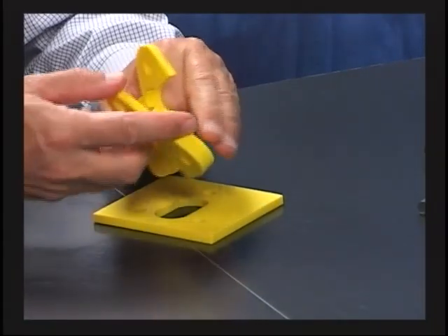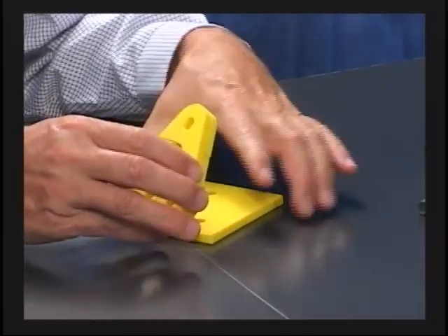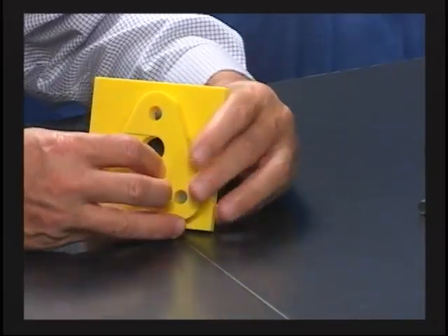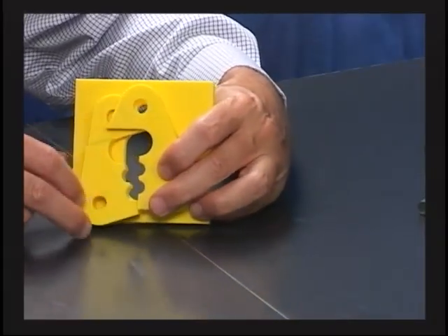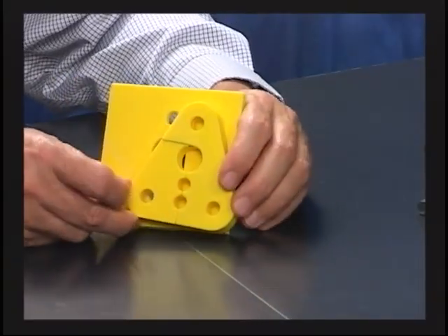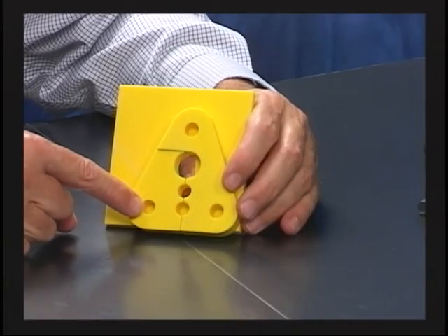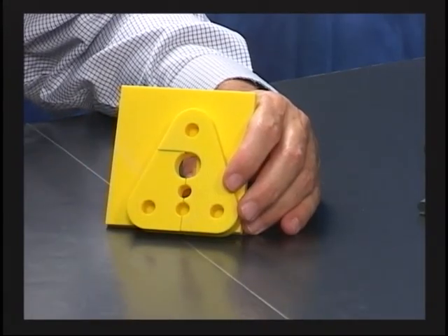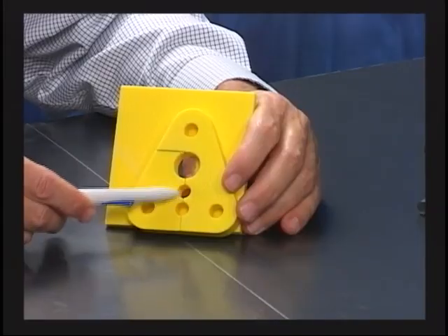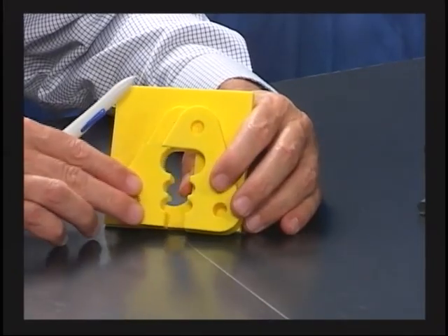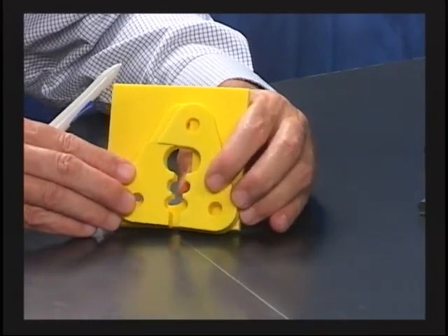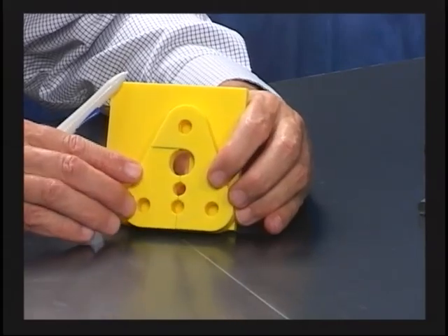Now, I see sometimes people say, well, why not just pick the holes as your datums? And I suppose you could. You could pick the holes as datums and then locate the surfaces. But the problem I thought is, if I pick the holes as datum and call those holes 0, then I'm going to have to tell you how much this face can be off. And I don't want this face to be off. I want the faces to come up tight. That's where they mount. They mount up tight against those faces.